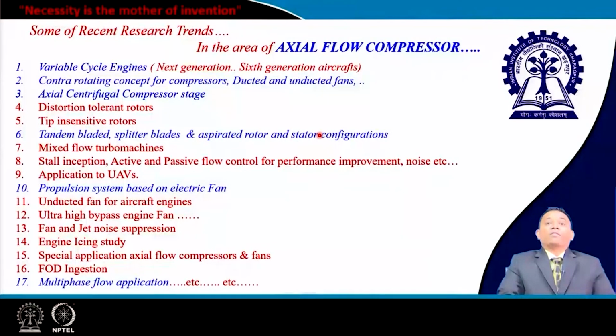Now let's see what people are working on throughout the world in terms of, say, axial flow compressors as well as fans. So the recent trend is the development of 6th generation aircraft, for, say, aero engines or fighter aircraft, where people are talking about the variable cycle engine, in which we will have our stator to be variable, which is a different requirement. So the design for such a stage is really challenging.